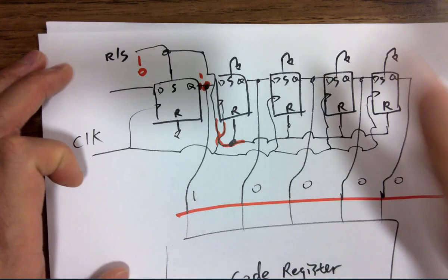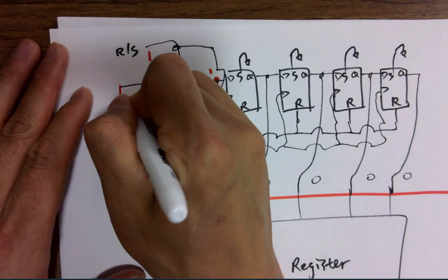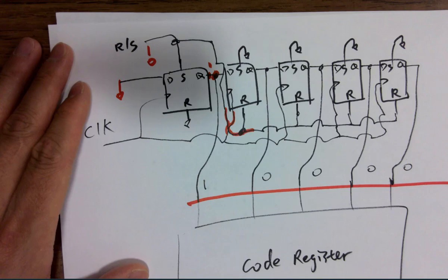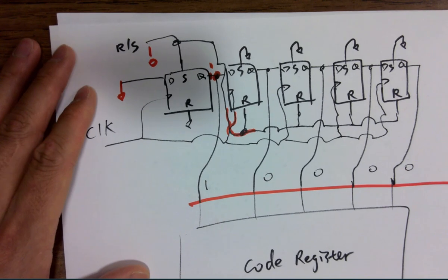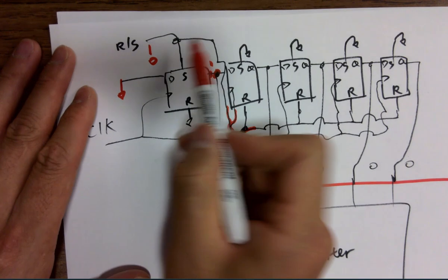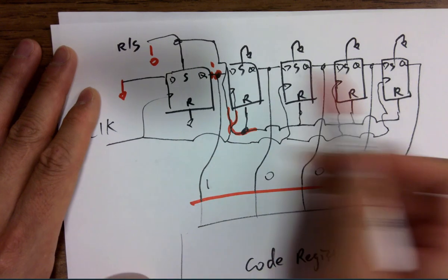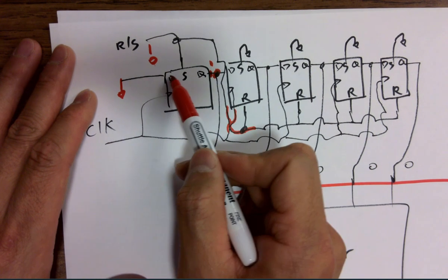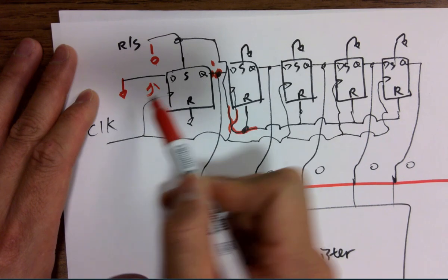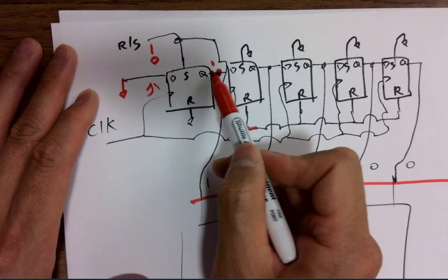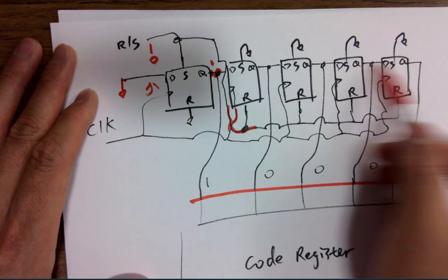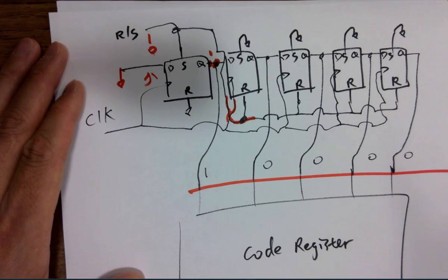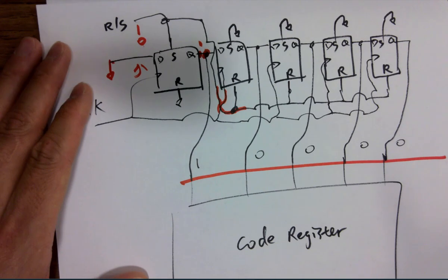Make sure you have a 0 on the input D. You set it at the very beginning, and then whenever you give a 0, you enable the D flip-flop mode, and whenever the clock's rising edge arrives, because this is shorted to ground, 0 will be passed to the Q, and also to the following ones in the following cycles. Does that make sense?